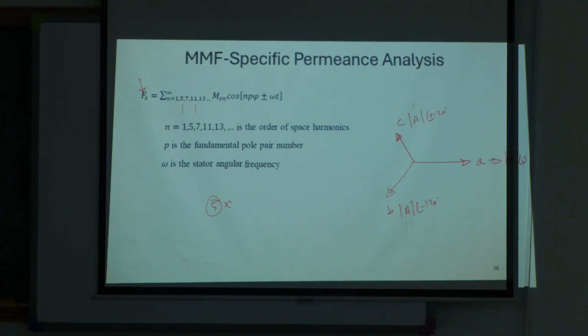If I do 5 times the angle, 5 times 0 is 0, 5 times minus 120, what is it? Minus 600. 5 times plus 120 is plus 600. Okay. So in a circular frame of reference, when I have 360 degrees overall, 600 is nothing but 360 plus some angle. 360 plus 240. So if I go around, this is 360 and then another 240 will be here.